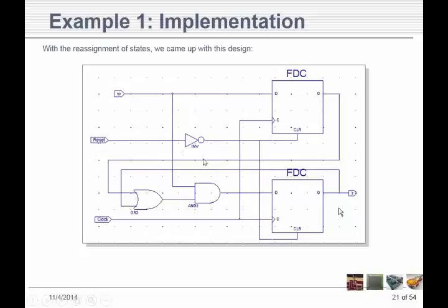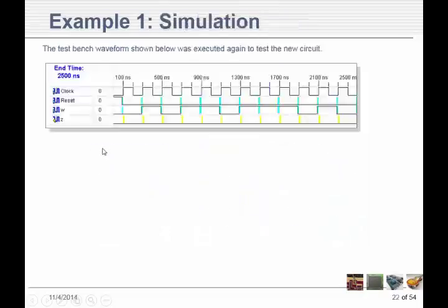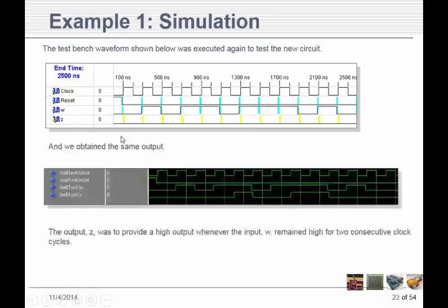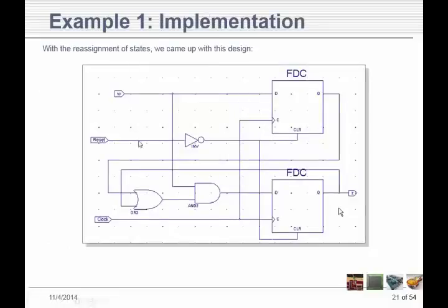Now here I put an inverter in for both of them, so I have to have reset low, then that'll make sure this is high. Okay, so that's like putting a bubble on both of those. But I could have reset go low, and then this thing is operational. I had it go high at the very beginning, so it cleared it out and we had a place to start.